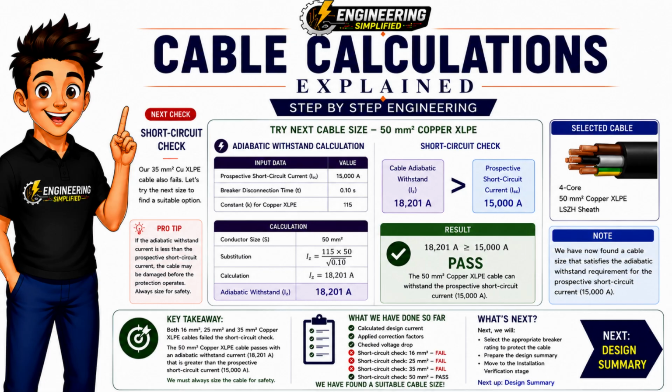We still haven't reached a safe design, so we'll increase the cable size once more. Finally, let's try a 50 square millimeter copper XLPE cable. Repeating the adiabatic calculation gives a withstand current of 18,201 amps. This time, the cable's thermal withstand current is greater than the required fault current of 15,000 amps. That means the cable can safely survive the fault until the breaker operates.